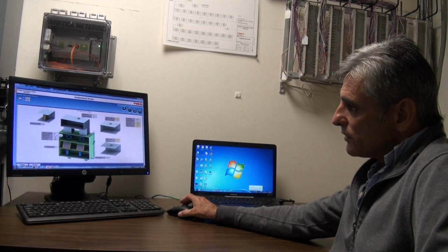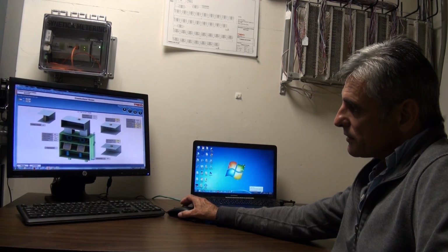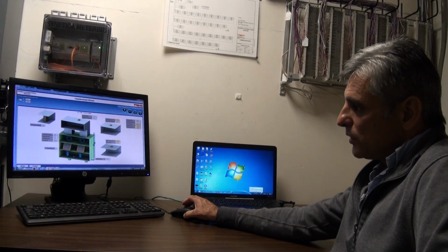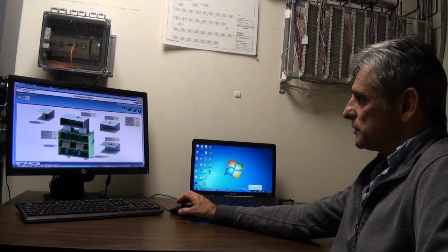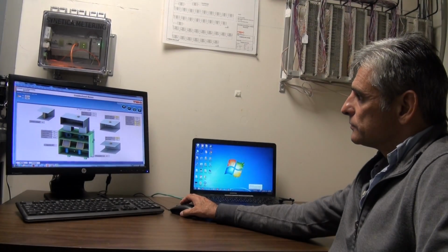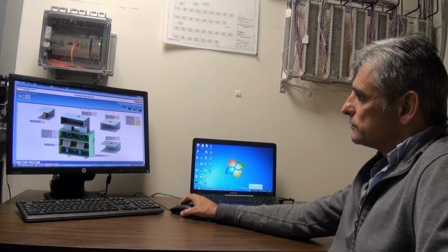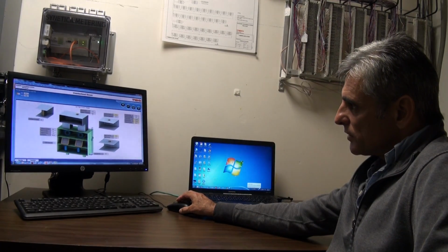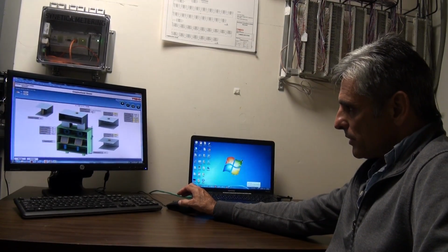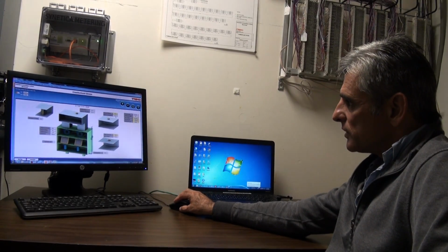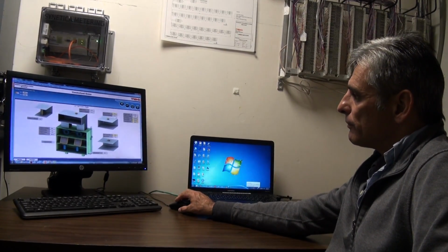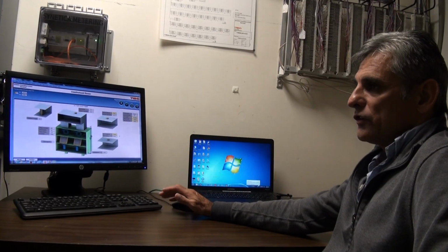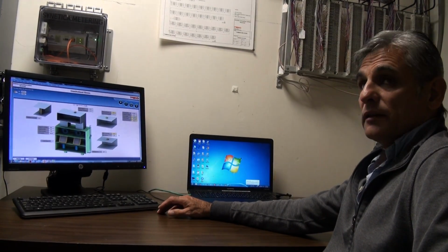As you can see, fan speed is running up to 72%. We'll start to see one stage of cooling come on very shortly, and then it will go through its normal stage cycle. As soon as the cooling stages begin, we'll start to see that supply air temperature drop. And we should also start to see the return air temperature drop. The whole staging takes anywhere between 10 and 15 minutes.